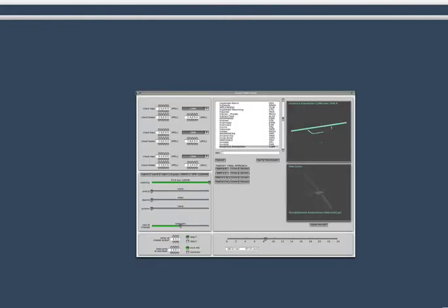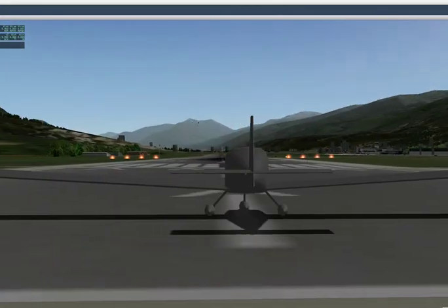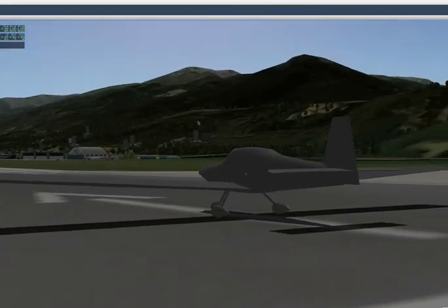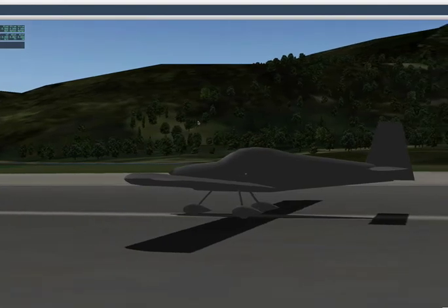So there's the plane. If I hit it here and I look outside, there's my plane with a 50-foot wingspan. And now I can take off. I can measure my takeoff distance, and I can see how aspect ratio impacts takeoff distance. If you can, go ahead, use the 50-footer and take off. Then make the aspect ratio with the airplane with a 10-foot wingspan and take off.